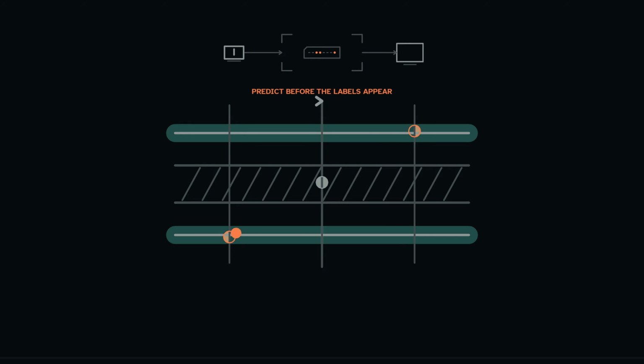Try the rule before seeing the labels. Measurement A sits well inside the lower valid region. Measurement B sits in the middle. Measurement C sits well inside the higher valid region. Which measurements may the receiver classify safely? A is safely lower, C is safely higher, B is neither promised result. Choosing whichever side looks closer would invent certainty that the physical contract does not provide.